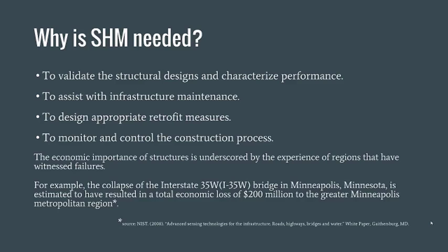SHM, or structural health monitoring, is not only useful for maintenance after the structures are built. It is also useful to validate the structural designs and characterize the performance, to monitor and control the construction process, and to design appropriate retrofit measures.